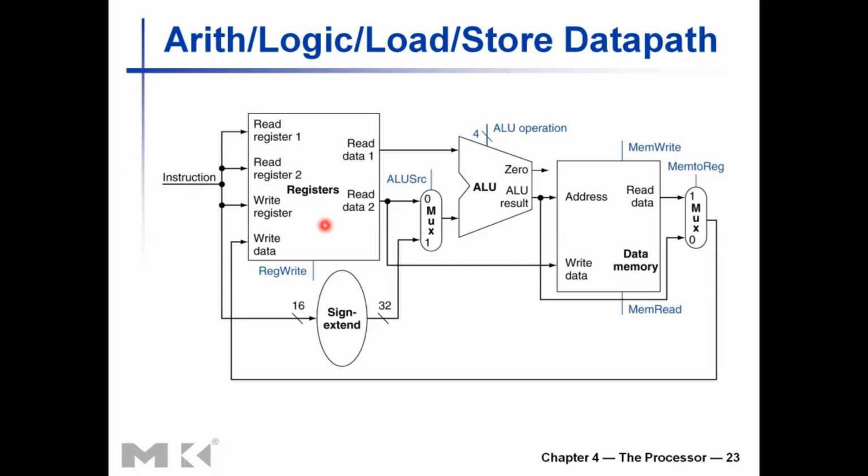If you're dealing with a load store instruction... if you're dealing with an R-type instruction, you don't have an immediate value, right? There's no immediate value given in the instruction. But you take the 32-bit instruction and send the different fields here into the register file based on the opcode, right? Since all these circuit executions happen in parallel, not like code that we write in a programming language,